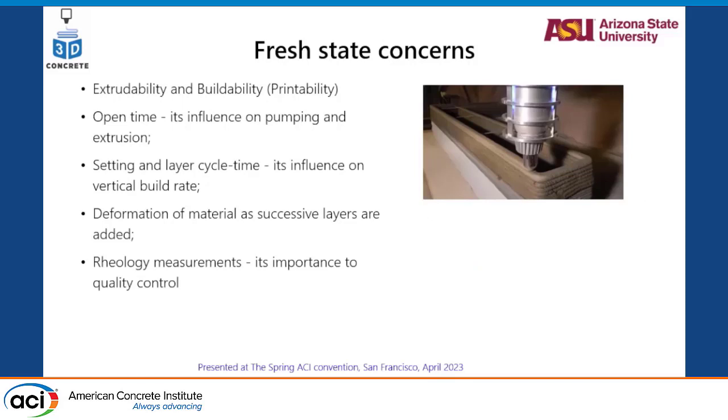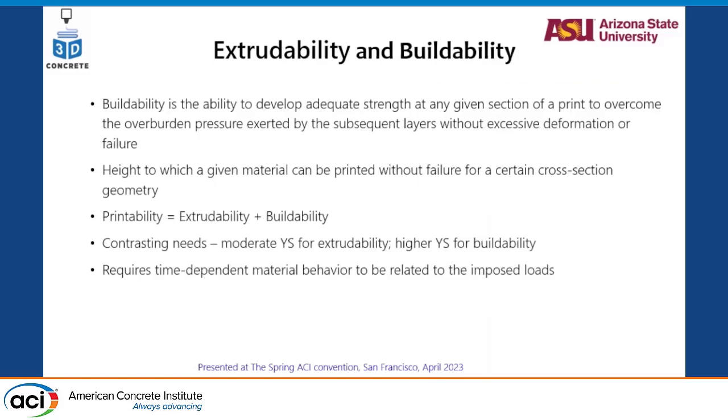The lack of a mold results in this: if the cement matrix becomes too soft, we may extrude three or four layers and it just collapses. While doing a print, we don't want just three or four layers to be printed. But how do we know how many layers it can print? Either by seeing the collapse, after which we could do nothing. It's just done, so we'd have to reprint everything. So a proper and more accurate theoretical model to analyze the buildability rate of a mortar was required, not just for one mortar, but for any printable mortar.